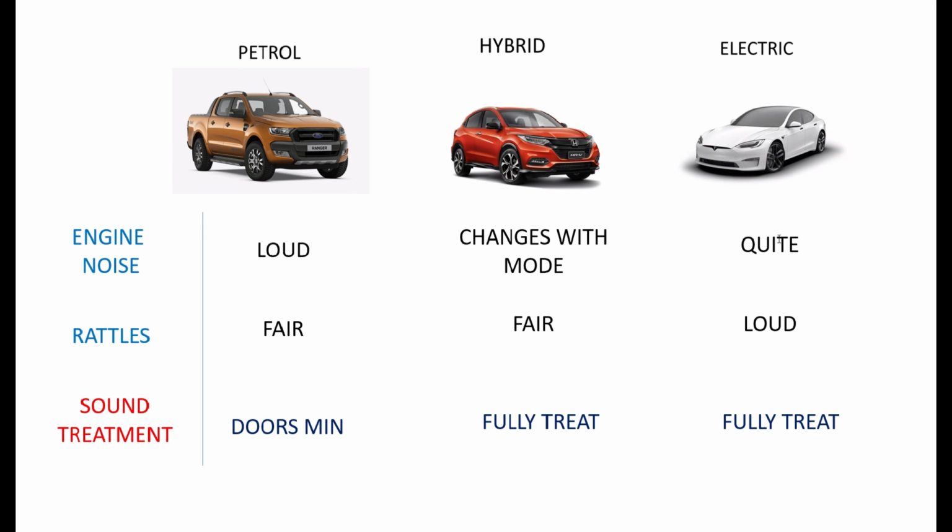But with an electric vehicle, because there's no engine noise, you tend to hear the road and tire noise, the wind noise, and all the squeaks and rattles in the cabin a lot more than you do in a traditional car. And so it's actually louder, which sounds almost counterintuitive. So sound treatment really is good return on investment in an electric vehicle.